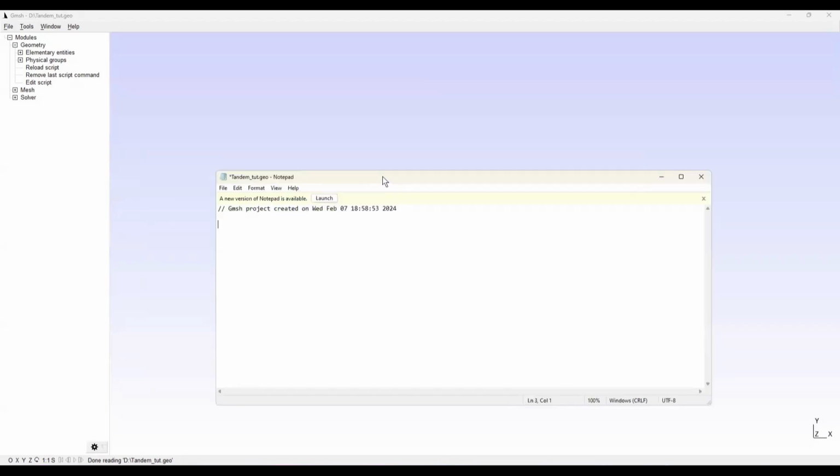I'm first going to specify the dimension of the system, which we're going to call 0.1. Then we can go ahead and give the first airfoil points. To do that, we're going to go Point, bracket 1. That'll specify point 1. We're going to go equals, and then 0. It'll go x, y, z, and then 0.1. You can see in the bottom right we have our axis. We're going to make this our center point. So it goes 0, 0, 0, and then 0.1 at the end.